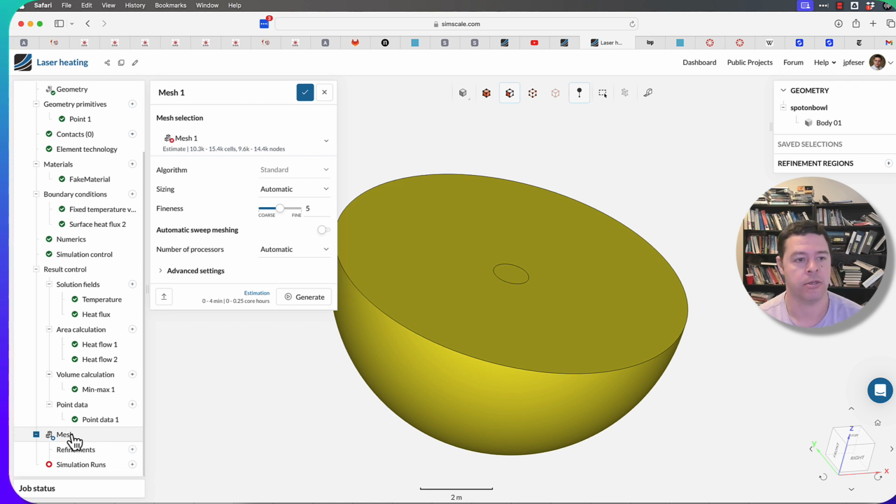Yeah, so it's going to design a mesh that basically follows your geometry and tries to make equally sized elements as best as possible with, quote, a good shape, which usually means equilateral tetrahedrons are the optimal shape if you're using tetrahedral shaped elements, so like triangles. So that's what it's going to try and do.